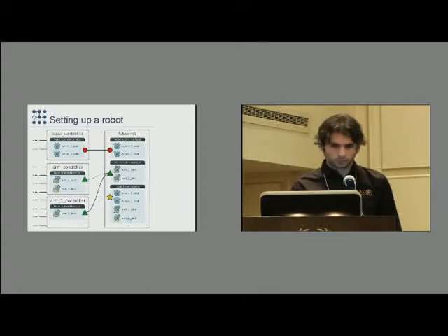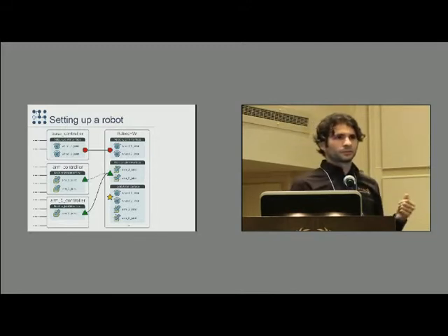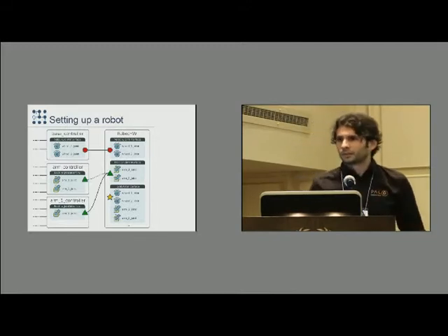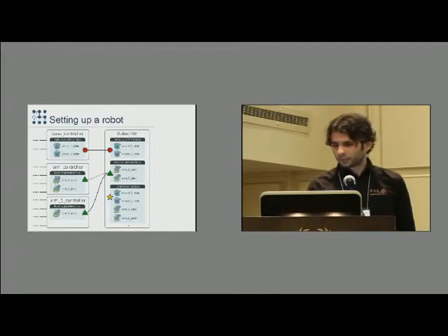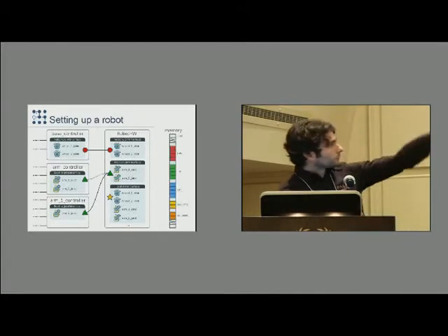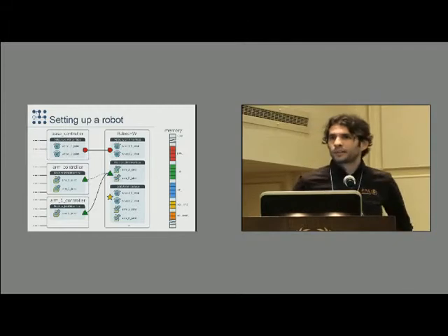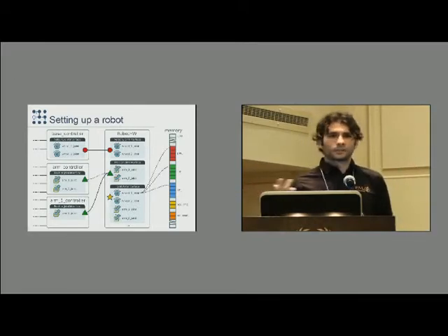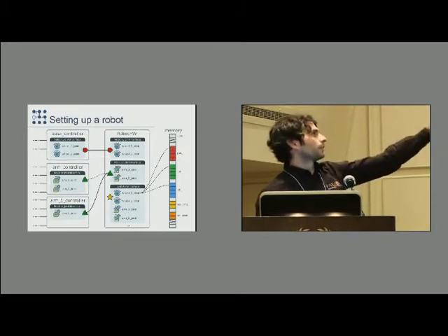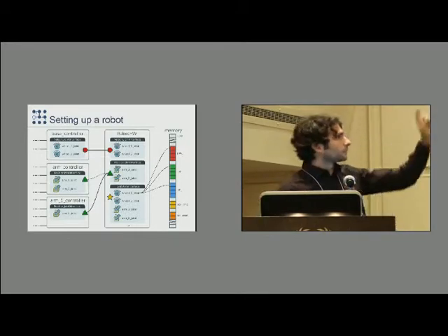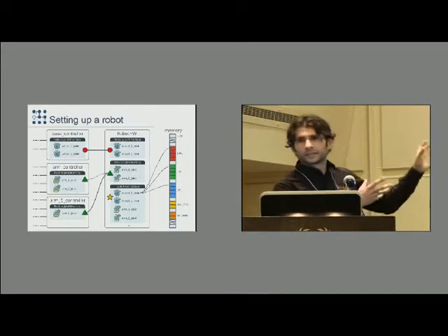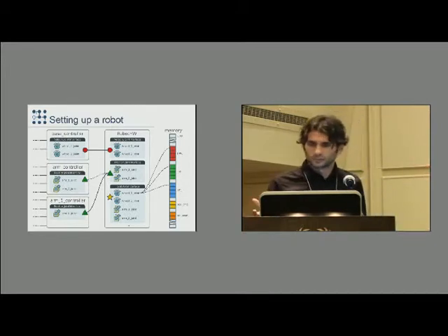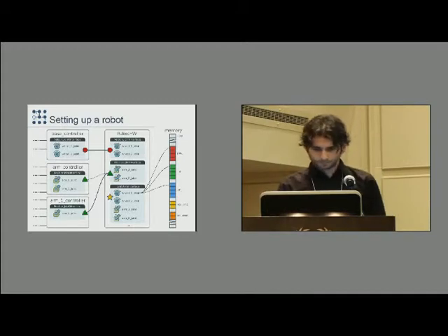Okay, so this is really nice, but how do you ground this to doubles and floats and the actual data that you want to pass around? So this here is supposed to depict the memory layout of your raw data. These are the memory regions where you actually read and write to and from hardware. So a resource is nothing else than pointers to the raw data that add some semantics, like, okay, this is position, this is velocity, this is the name of the joint, and it belongs to a joint state interface. The idea is really simple.